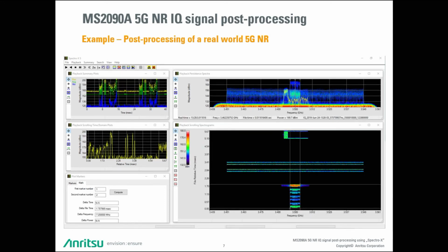This slide shows the final results of our measurements. The following video sequence gives you a live impression of how easy such analysis can be for you. First of all, load the converted file in a Spectro X readable XDAT format and next arrange the settings either manually or, as we do here in our example, just load a predefined setting file. Finally, play the file on different zoom levels and operate the markers or other analysis features for a more in-depth signal analysis.